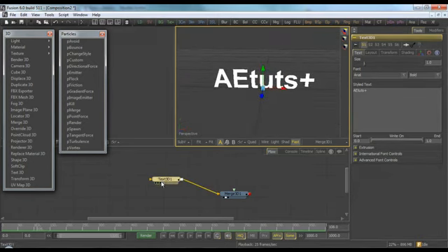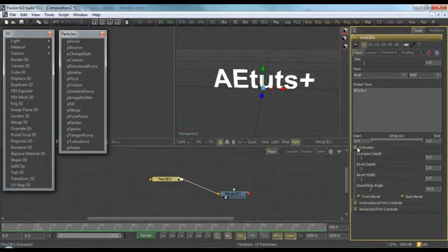And how do we make it 3D text? We have to make some adjustments, like extrusion depth. We'll set it to 0.05. We don't work with such large values because I decided to make it small. I mean, small world, ant world. So extrusion depth 0.05, and bevel depth will also be 0.01, and bevel width even smaller,